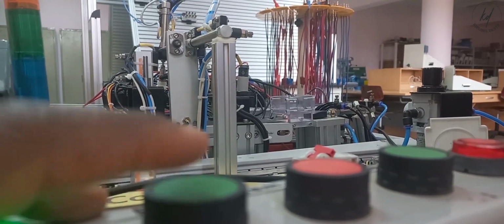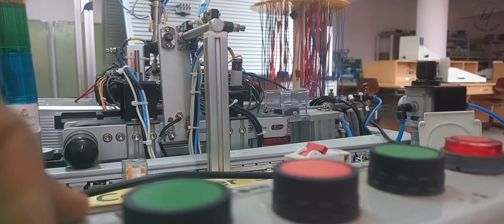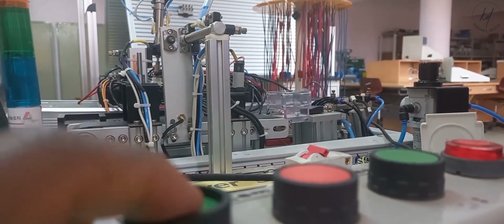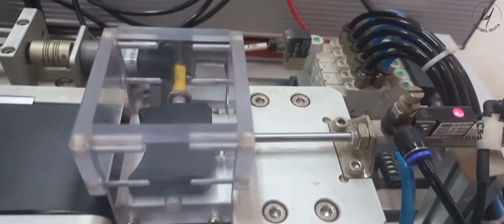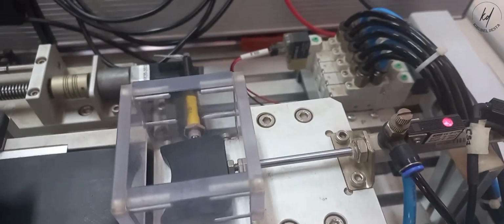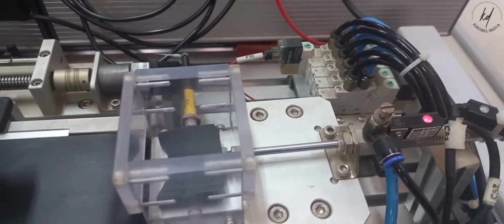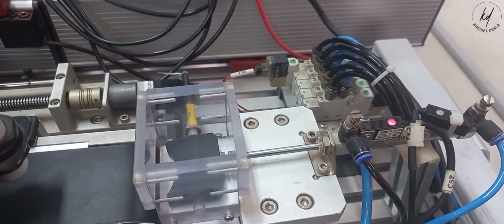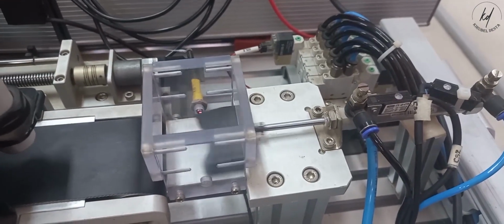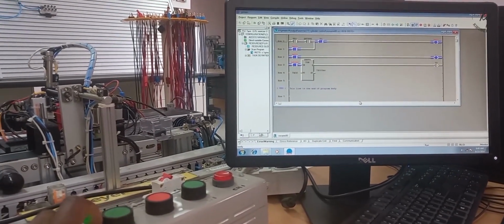By default, the cylinder stays in the retracted position, and when its coil tag gets power supply it becomes activated and now advances its cylinder pneumatic piston. Otherwise it will stay in the retracted position. From the ladder diagram you are looking at, energizing the coil tag to advance the cylinder piston depends upon the on timer normally closed contact and push button 1, in addition to the retracted state of the piston that have been set.